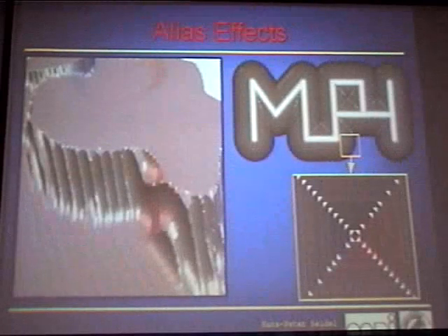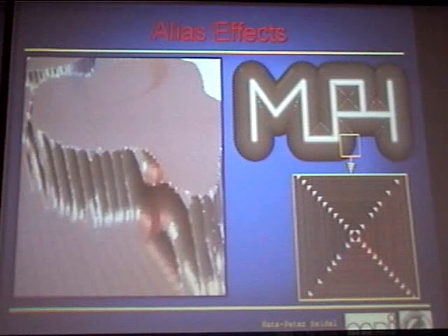Now it's known that the standard marching cubes algorithm has a severe aliasing effect. What you see here is an example of an NC milling simulation, and you can see it whenever there are sharp corners. This was a simulation that uses a volumetric representation. If we extract the isosurface, then we have severe aliasing effects, and we're no longer able to judge the quality after running the simple marching cubes algorithm.